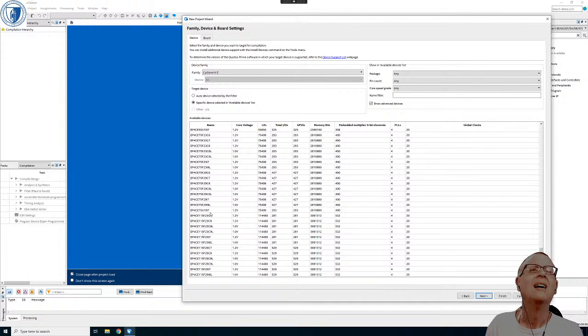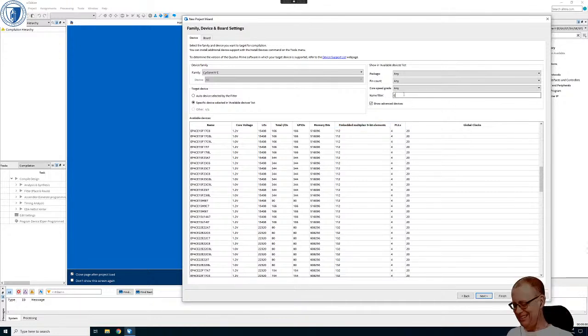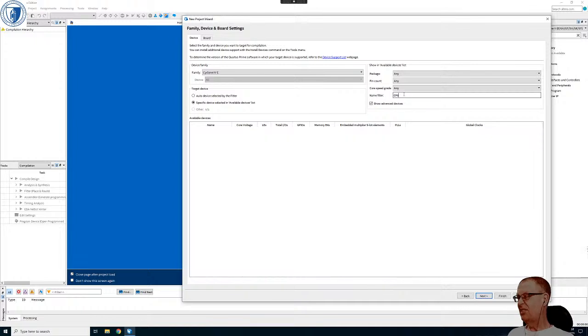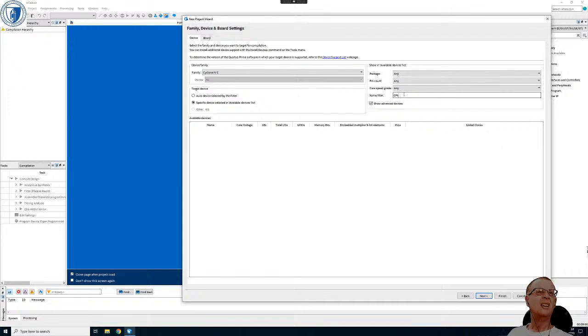I'm sure it's here. I saw it the other day. It's a little far away. You could put the name in the filter. Where's the filter? Oh, you're right. Let's do that. Thank you. EP6. I see there's two versions. There's one without the L, and then there's one with L, with a core voltage of 1.2 volts, and the other one just 1.0 volts.